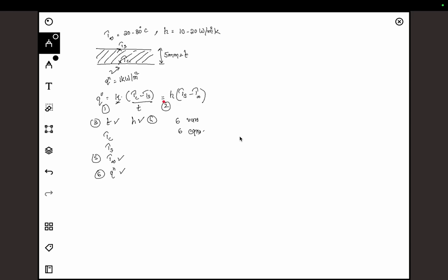So how did you go about picking the values of H and this T infinity? Okay, you have chosen H equal to 10 because you want the maximum temperature of TC. Basically we don't want the material to have, from material constraints, maybe the material is unstable beyond a particular temperature. That will be a limitation given by your material engineer. So from the catalog we found that 150 Celsius is the maximum temperature you can go to. So the temperature here cannot exceed 150.